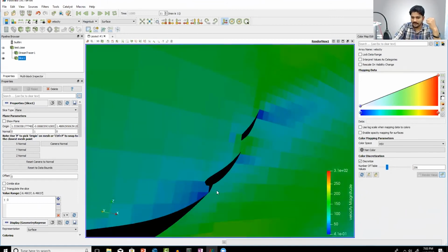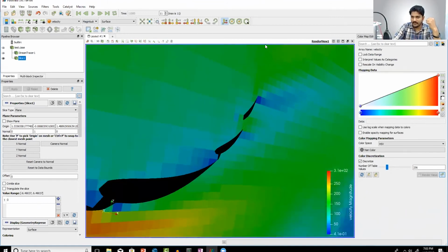If you look at the cut plane, right, you can see that between here, where is my drawing tool? So here you can see that there's a disconnect. Maybe I'll use a black color. Here you can see that there's a disconnect, but here you can see that things have been joined. In fact, this flow path is very crucial because it helps in energizing the boundary layer, which is very important because that helps you in preventing flow separation, which is a very desirable outcome whenever you do aerodynamic analysis, because that helps you in reducing drag forces.